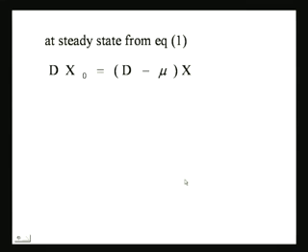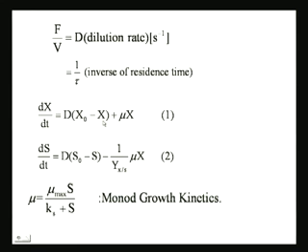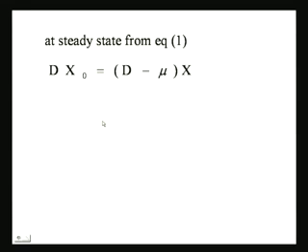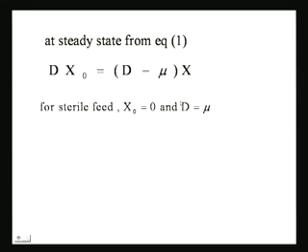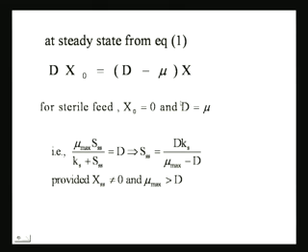What we are going to do from now on, in today's class and next class, is slightly hard, and you should pay attention to the process, what is really happening and how to do it, because then you should be able to do it for other kinds of systems. That is fine, right. So, we put the Monod growth kinetics in, and then we go for the steady state solution. At steady state, this is your basic equation: 0 equals D times (x naught minus x) plus mu x for the x equation, and similarly for the substrate you will have another one.